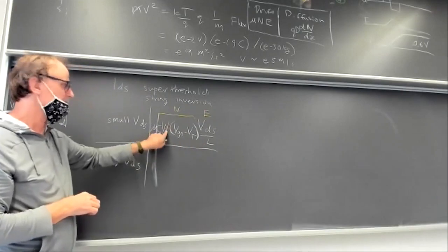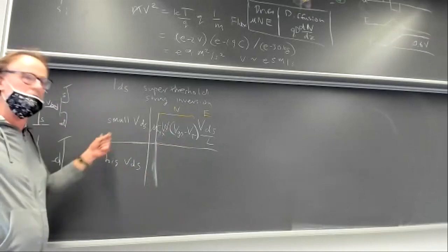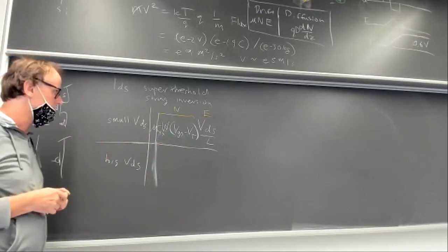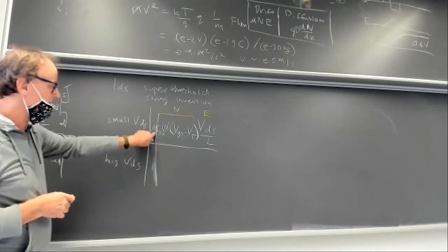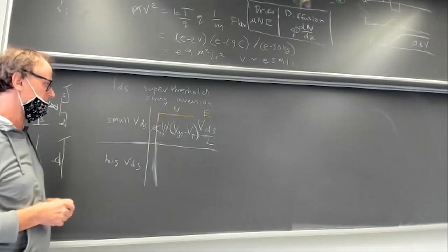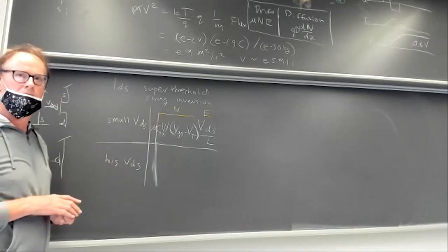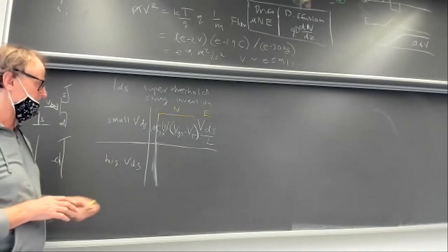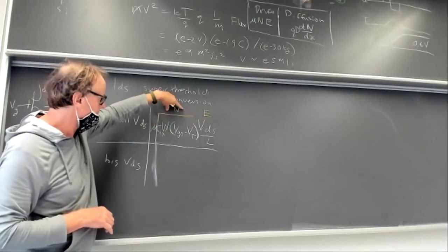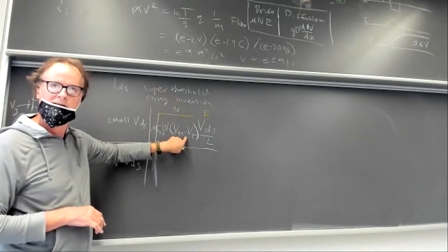Okay, and what is this W here? That's the width of the transistor into the blackboard. The wider the transistor is, of course, the more current you get. And the mobility here is just how fast the charge moves in response to the electric field. So that's the whole above threshold equation, which is a consequence of the drift current acting on the charge in the channel caused by going above threshold a certain amount.